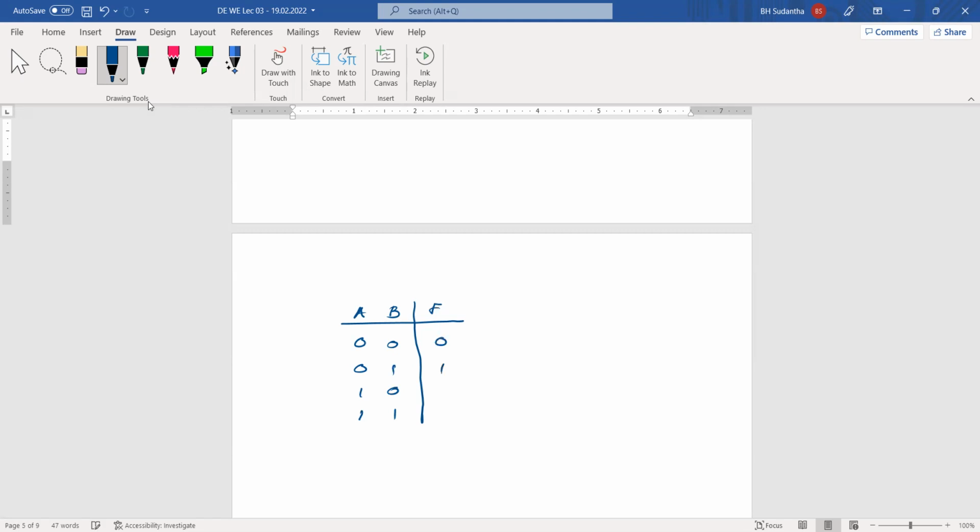This is the exclusive OR gate truth table. We know that this is exclusive OR between A and B. Okay. Then forget about this table. You can write the output equation by considering these ones. For that, we can consider this one and this one. Then we can write the output equation for F, that is A bar B plus AB bar.